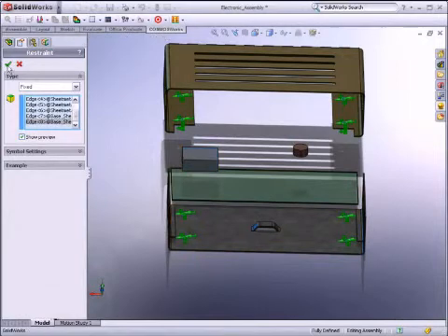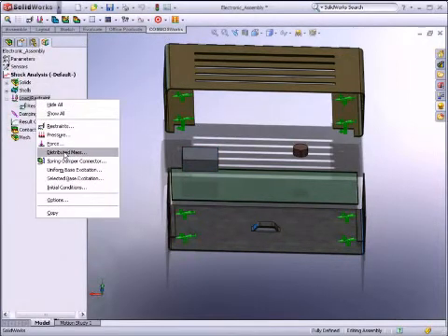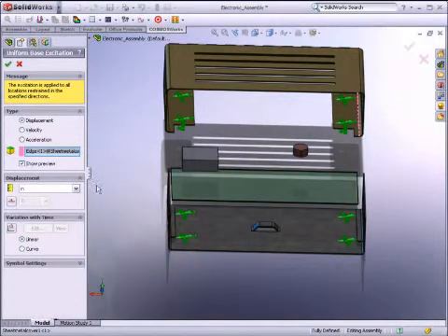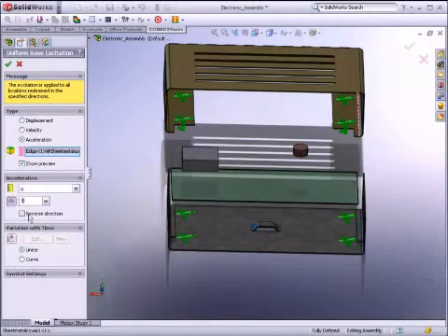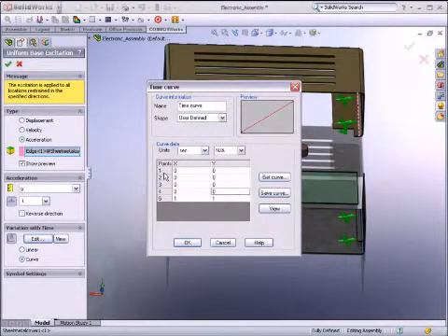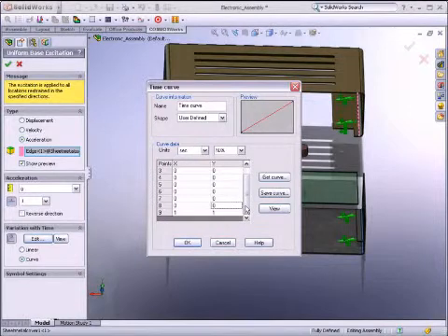You can select the load type from a list, in this case, uniform base excitation. Then indicate the edge where the excitation will occur and that you are going to use an acceleration type. Next, specify your acceleration value, in this case 1g. We are going to use a curve-based variation with time, where we can enter the data directly or load the data from a file.